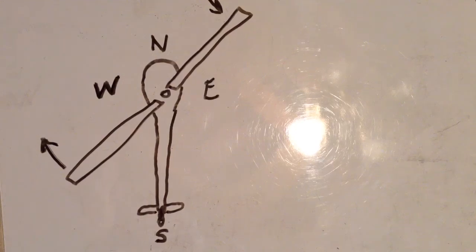So the lesson to be learned is that if you push up on a rotating body, it rises up 90 degrees, or 1/4 of a circle, past the place where it is pushed up. In other words, our helicopter rotor, which is pushed up more when it is on the east side of our helicopter because of the high angle of attack, rises to its highest position when it is behind the helicopter. When the rotor is swinging on the left, west side, where its angle of attack is minimum, the rotor is not being pushed up as much as at every other position. So the rotor swings to its lowest point when it is in the front, or north, of the helicopter.